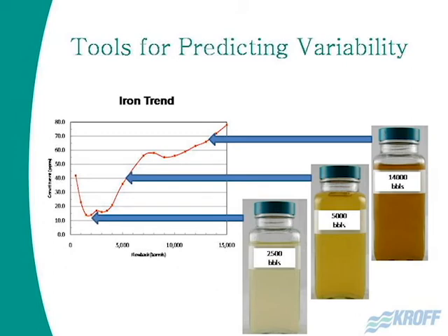This is iron coming back at various stages of the flowback. So if I'm an operator, I'm going to feed chemicals to remove the iron, but also chemicals to prevent it from plugging my sand filter up. Chelants, chemicals, acids, and things that keep it soluble, keep it flowing out of the sand and not being left behind as a particulate in your sand filter, just like a swimming pool.